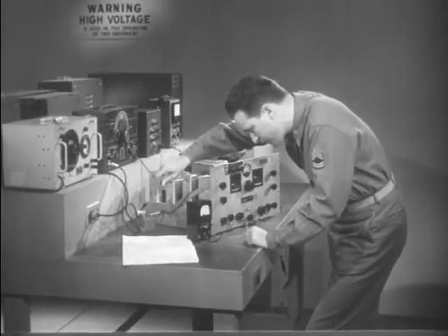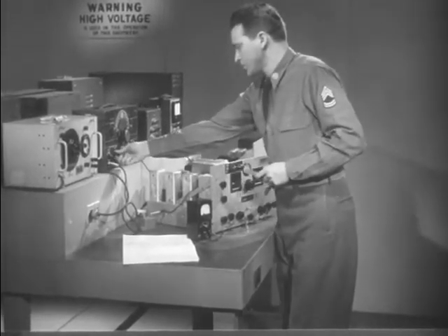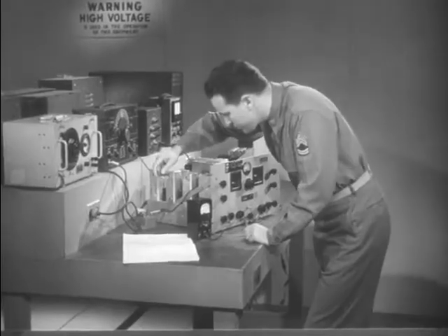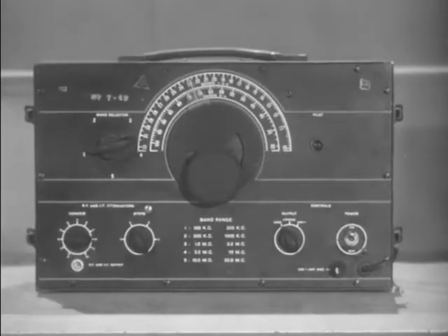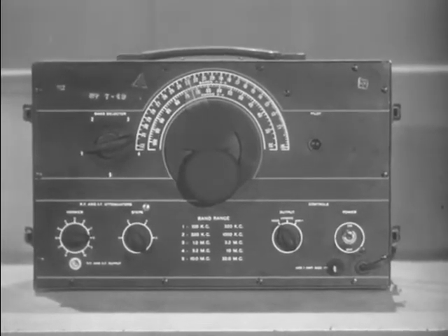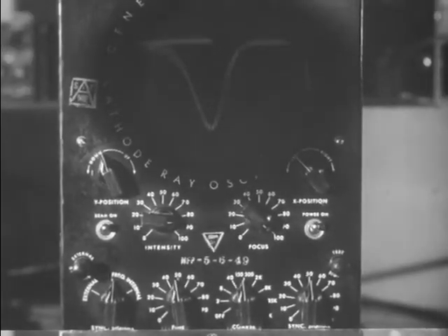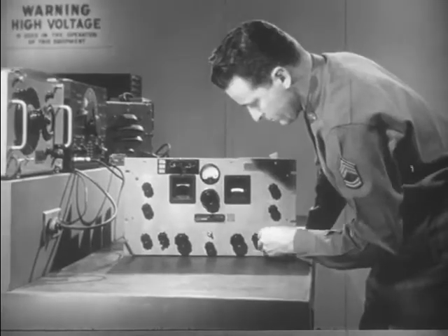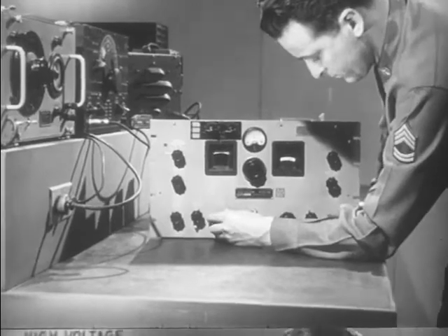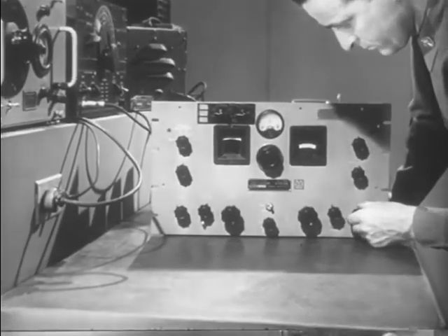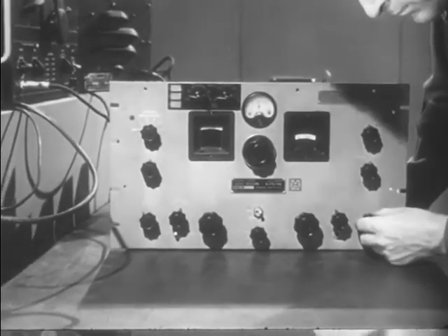Signal generators must be used in accordance with instructions contained in the technical manual pertaining to the equipment to be tested, as procedure differs with each piece of equipment. They must be used in conjunction with an indicating device. First, the signal generator transmits a signal. Then the equipment under test receives it. The meter or oscilloscope indicates the result. Take the trouble to learn how to use it properly, taking care not to damage it, and the signal generator will soon be helping to keep your communication equipment at top efficiency, making your job seem less like work.